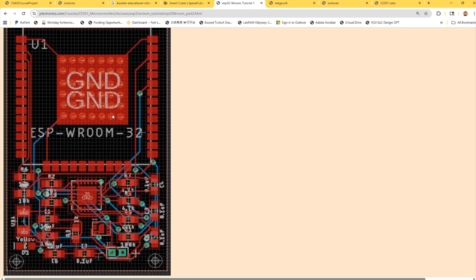If you have a 5 volts power supply from USB and you regulate it to 3.3 volts, it's easy because there's like 1.7 volts room to drop. But from 3.7 volts to 3.3, you only have like 0.4 volts to drop, and most of the regulators cannot do it. So I have to use a certain regulator like this one, which has a low dropout voltage, so it can convert 3.7 volts to 3.3 volts.